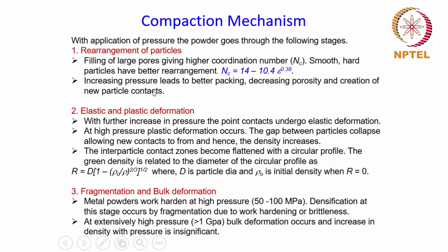Increasing the pressure leads to better packing. That is obvious. As you apply more pressure, the particles pack together and the pores in between them will decrease, and as a result of that, the porosity will decrease and it will also create new particle contacts, right? So that is how the whole rearrangement process occurs.